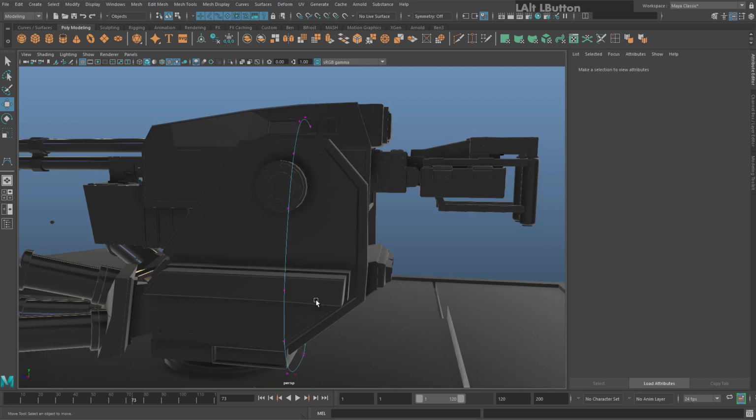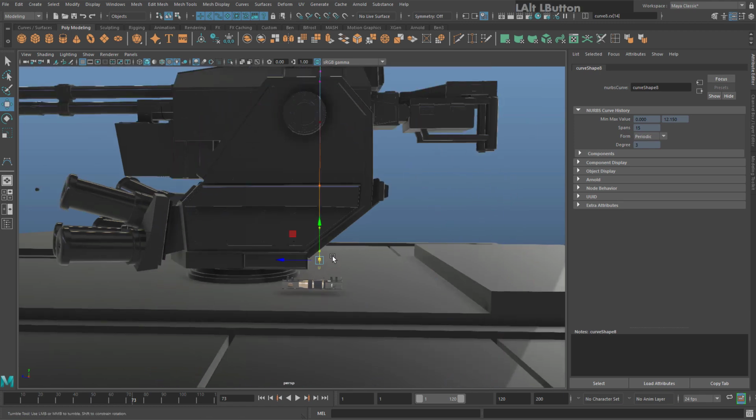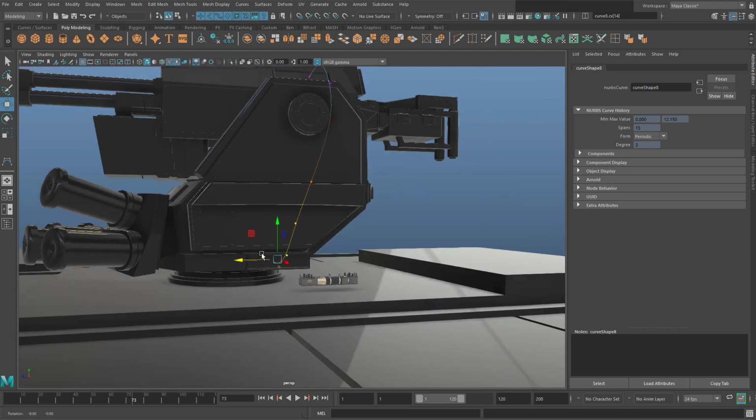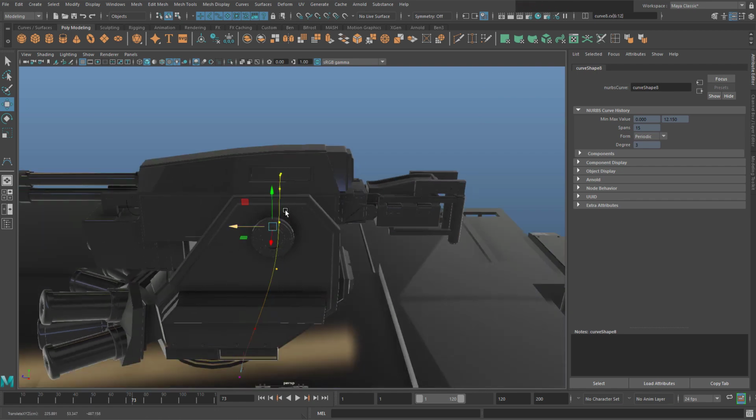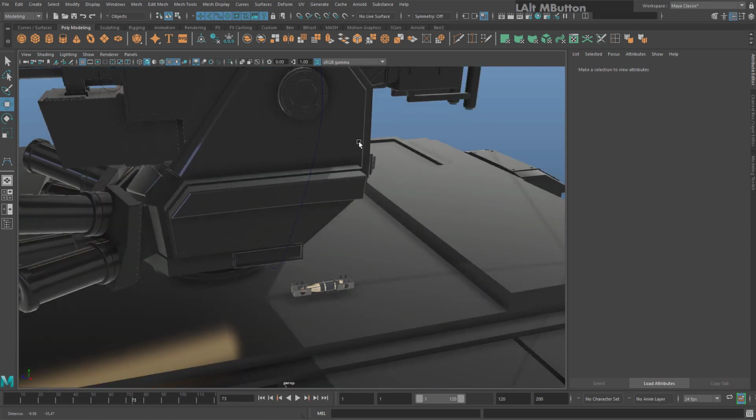I'm going to go to Control Vertex and drag select the vertices at the bottom, hold B for brush, and soft select by holding the letter B and kind of move this that way, and that should work nicely. Go to object mode to come out of there. You can tap B on the keyboard to get rid of that.